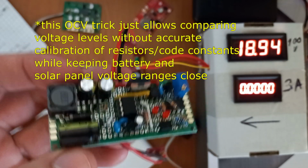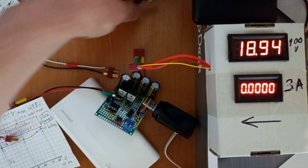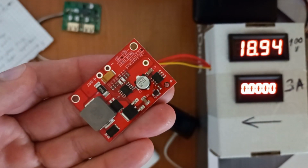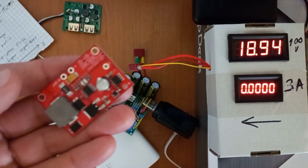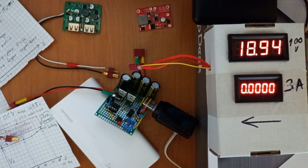Overall, it's around 60% more efficient than this particular claimed MPPT lithium-ion charger, and I tested this. I want to make a separate video about it to tell more. If you don't have reverse current protection, the real reverse current in the panel when it's dark is very small, according to my test. For an 18 volt 50 watt panel, it was 2 milliamps from a 12 volt battery flowing to the solar panel.